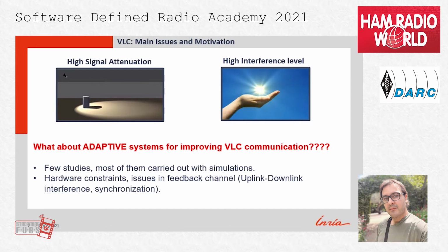But especially in the latter case, speaking about outdoor applications, there are some issues. In fact, different from lasers or optical fibers, VLC exploits low power energy with wide light beams and often in an uncontrolled scenario. This causes two big issues. The first one is the high signal attenuation, and the second one, especially in outdoor scenarios, is the huge interference of other light sources, namely the sunlight.